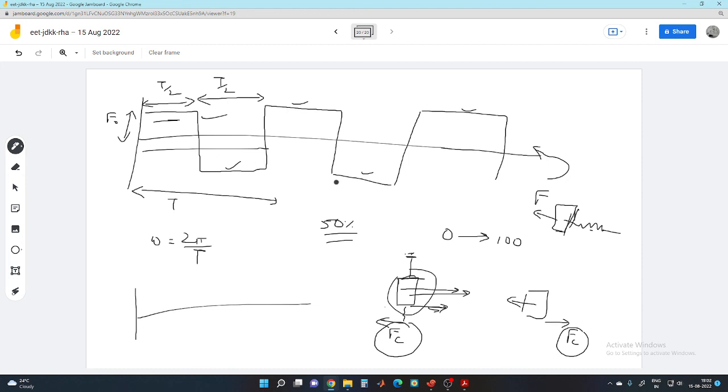Then there is this triangular and step waveform. The Amazon guys or any packaging agency actually model the impact response. So what they do is they have this packaging. They analyze how much damping, how much stiffness and other parameters should be optimized such that the package experiences a below critical limit of acceleration so that the internal components of that package are not damaged.